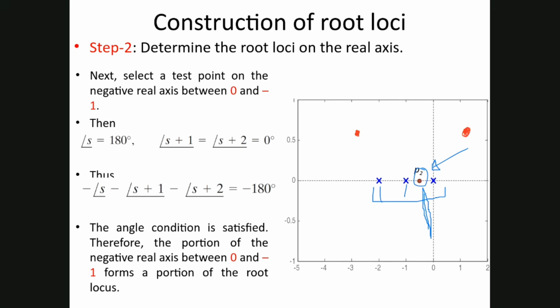So I just want to check. Let's say I am having the root locus like this. The red one I'm just plotting, just some kind of root locus, I'm just giving you an idea. Let's say your poles have this kind of locus, like they have started from here, open loop poles 0, -1 and -2. This -2 pole is going to the deeper side of the S plane as you increase the gain k.